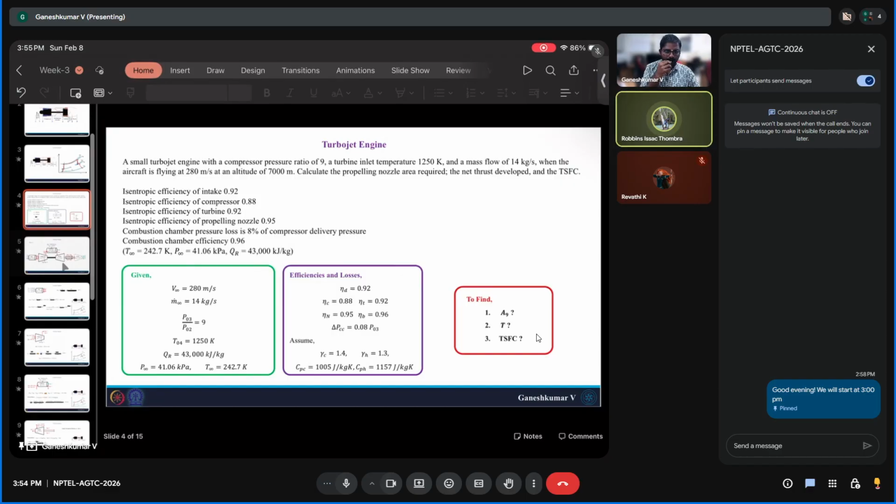Sir, I don't know whether this is covered in the topic, but just for my curiosity, I work in aviation. Normally I think this topic covers only two-spool engines, and Rolls-Royce and others use three-spool engines, which have an IP, an intermediate pressure compressor also. So I hope in that case the station numbers will also change. The engine station numbers will be different, instead of 02 to 03 being one set of compressor. Yes, this will change.